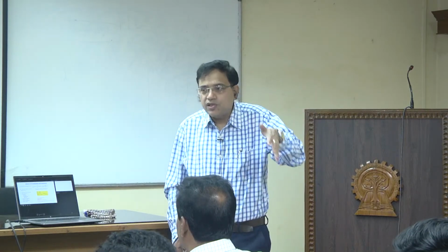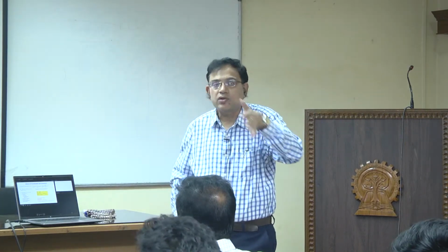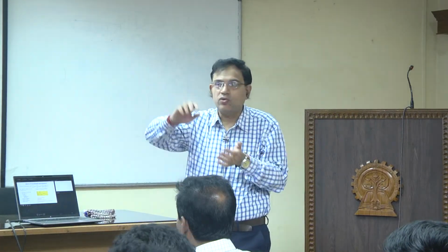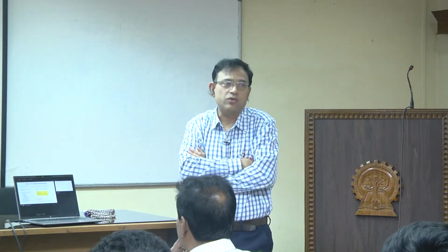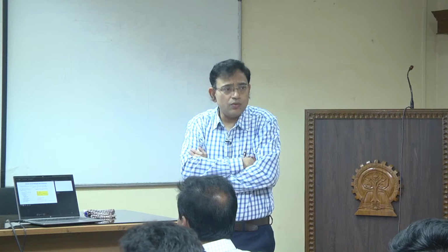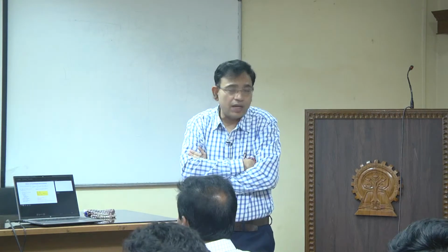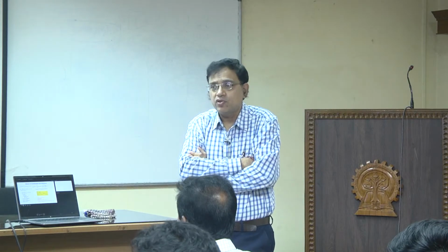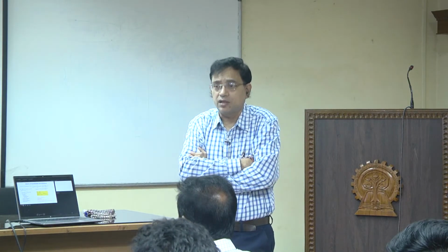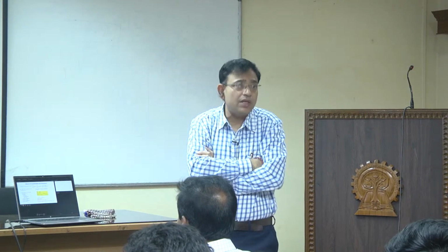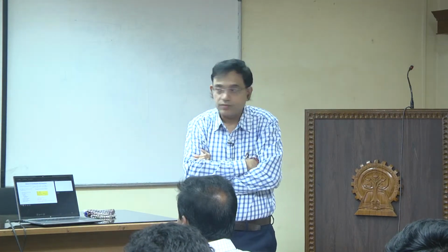So that thin region, how it is growing over the solid boundary is the growth of the boundary layer, and that growth of the boundary layer over that coordinate is like a one way coordinate system. So there, although it is space, it is giving a time like coordinate. So one way is not always time, but it is a time like coordinate, and whenever you have a one way coordinate it is like time. So you can give something like an initial condition, although in a physical sense it is like a boundary condition, but in a mathematical sense it is like an initial condition.